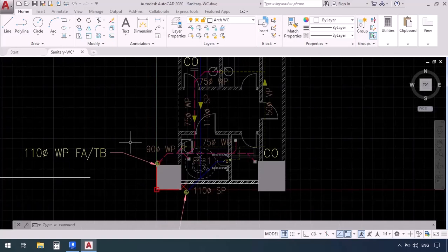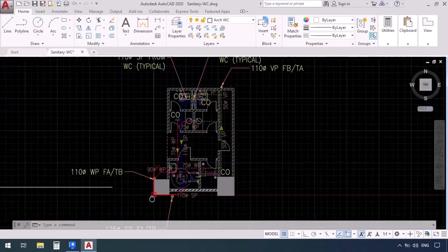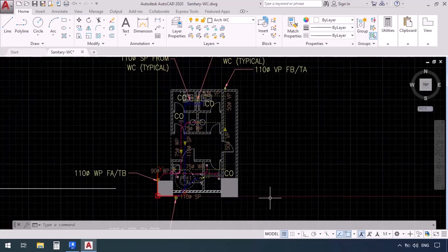Now, the reason why we have two different risers in this project is actually because the light waste is supposed to reach the refinery. That waste would be refined, and that refined water would be used for things like irrigation, watering, or just washing in general. But the heavy waste would be collected separately so that it is disposed. So remember, maybe not in every project the heavy and light waste would be separated, but here in this project there was a solid reason for that.